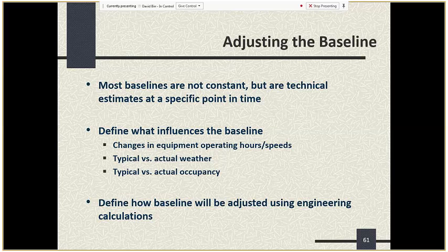We already touched on a few of these, but a couple more would be weather and occupancy. For example, when we did some utility bill comparisons to cross-check the option A and B methods that JCI was using, and compared 2011 to 2015, we found out that occupancy at OGG had gone up about 20%. That's great for tourism and for DOTA, but it did put an additional load on the chiller system. And that would be an example where you had to take that into account if you wanted to use a cross-check of an option C method where you did some utility bill analysis against options A and B.